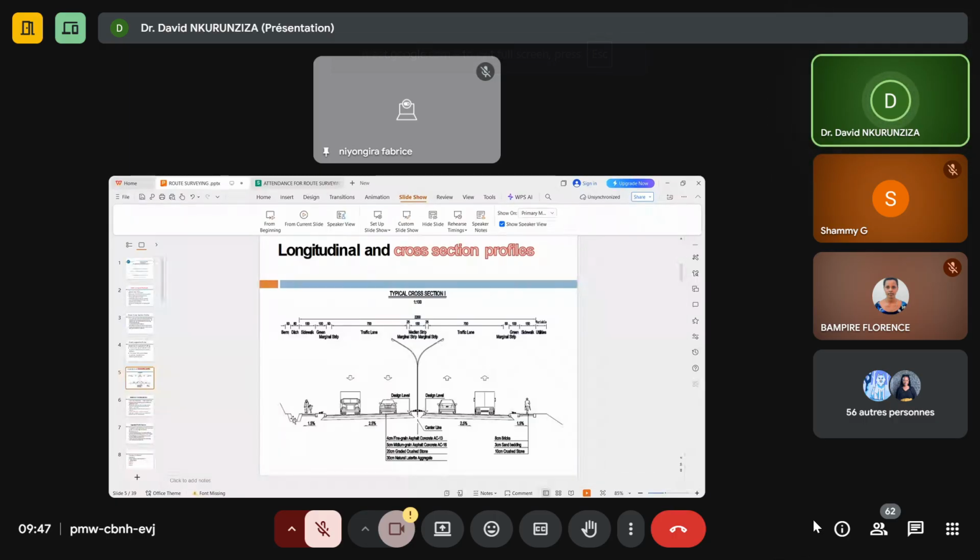You can see, for example, here we are having a drainage, as I have said. You can have a lot of elements along the cross-section profile. For example, this cross-section has the drainage here. It has a walkway, footpath here. We have a greening part here. This is a traffic lane. This is the median. And this median strip is at the same time used as a place where we are putting the lighting, and also there is some greening you can see.